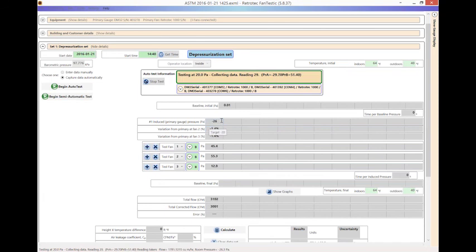So I have some slides later, which we're going to come back to. If you remember the red that showed up, we're going to talk about what that means in terms of where your fans are located, or that they're not actually able to gather the right data, or maybe there's something that's separated with their tubing. So again, you see it says 26.6 here at the top where it has its induced pressure. And remember, we gave it the ability to go above and below 15% or 3 pascals to gather data in order to perform the test.